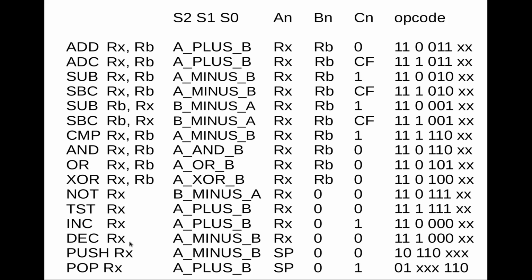And the decrease instruction, well, I've simply determined that I've reassigned the meaning of increase with carry, which doesn't mean anything, because that would in fact be an increase by 2. And okay, that's not an operation we want to support. So I've reassigned another meaning to that to actually correspond to the decrease instruction. And so again, for the decrease instruction, we've already determined what we need to send to our ALU. But in our opcode space, we'll simply assign that to this operation code, but then with a carry set to 1.